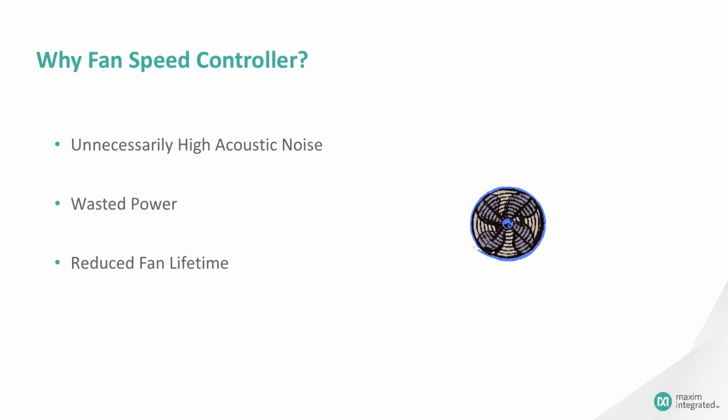Fans are used in electronic systems that require airflow to provide sufficient cooling for the various components. If you use a fan, or multiple fans, that can move enough air to sufficiently cool the system components under worst-case conditions, such as maximum ambient temperature or maximum power dissipation, that fan will keep the internal temperatures low enough to avoid component damage.